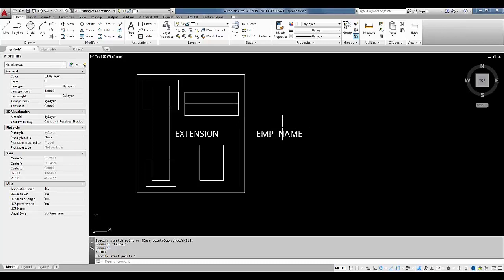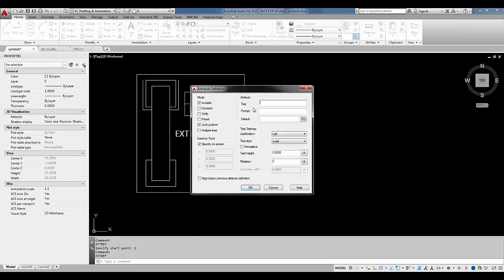I'm going to go ahead and do one more for this purpose here. The finished block with attributes that I'll show you later has a lot more information in it, but we'll just repeat this one more time. I'll leave this invisible, and this time I'm going to set it to preset so that I'm not prompted for the value of that particular attribute. And the reason why is it's the cost. And we'll just keep this under $150.